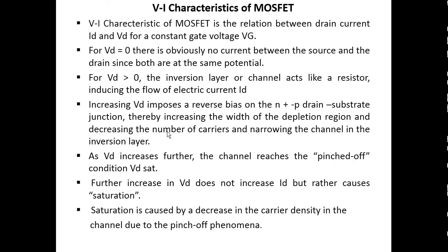Saturation is caused by a decrease in the carrier density in the channel due to the pinch-off phenomenon. Once the device is saturated, the carrier density in the inversion layer will be very low, and this decrease in carrier density is mainly due to the pinch-off phenomenon.